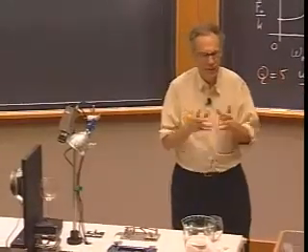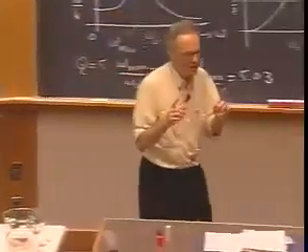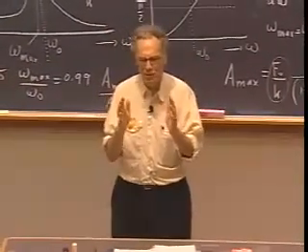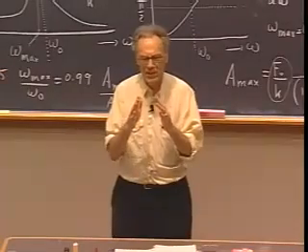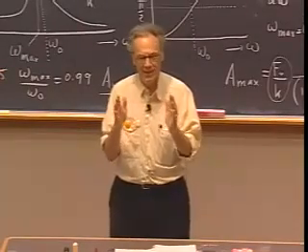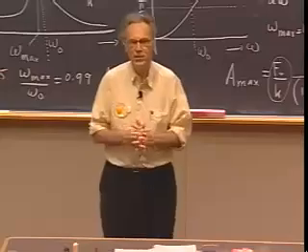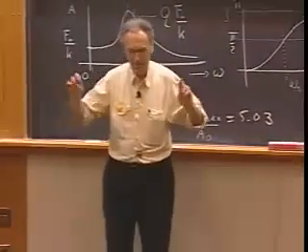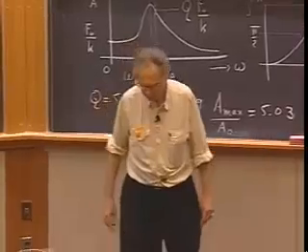And think about it. Two frequencies almost the same give you a beat phenomenon. So what that comes down to is you see the motion of the glass very slowly. And then if we hit that resonance frequency, we will increase the volume, and then maybe it will break.